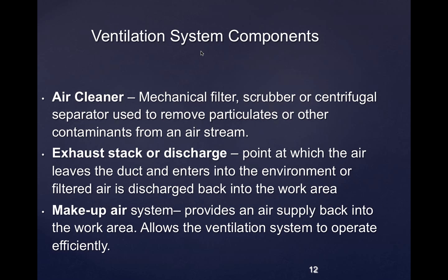So again, we reviewed the basic components of a ventilation system. You got a hood or some sort of device to capture the contaminant. You got ductwork. You have an air cleaner. Almost always have an air cleaner of some sort, because if for no other reason, you got to protect the fan or the other equipment, or eliminate a hazard that you might be discharging outside. You got the fan, which you need as an energy source to actually keep this whole thing operating, and you have an exhaust stack, right?